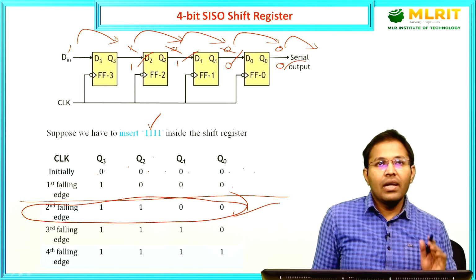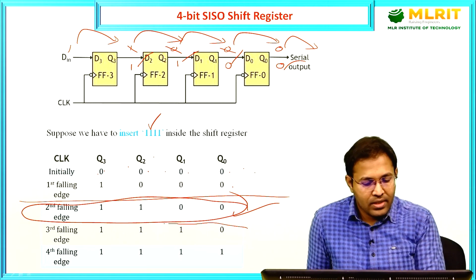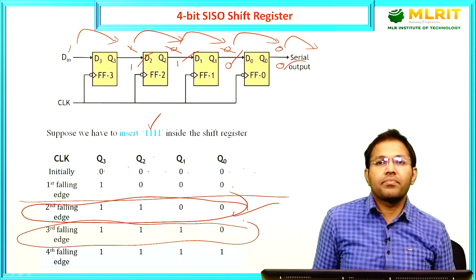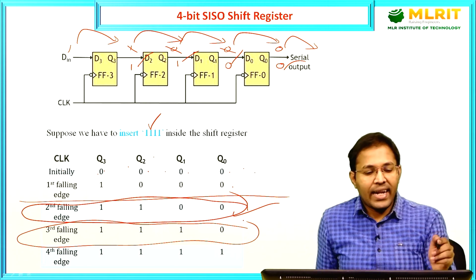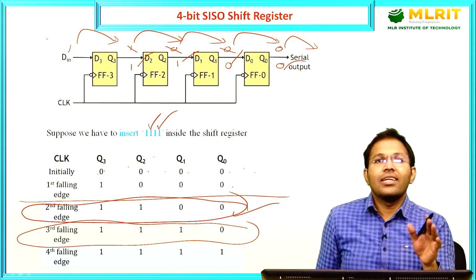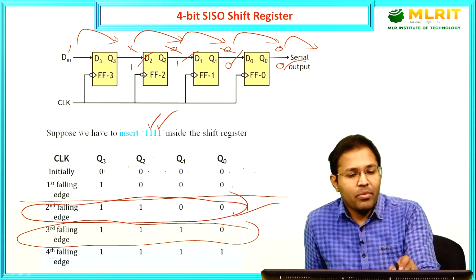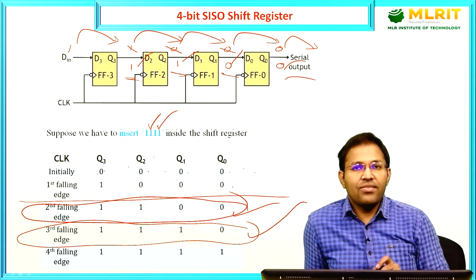Fine. Now we have discussed 2 cases. Now one more clock pulse. Okay, one more clock pulse. Each value shifts towards right, and remember we are giving again input as 1. Fine. So in such a case, what are we supposed to get? We are supposed to get 3 ones and then a 0, and that is what we have.